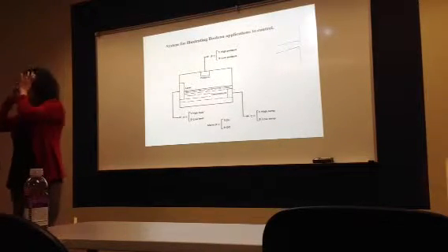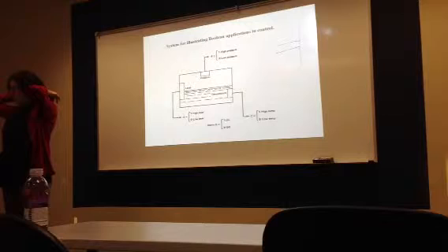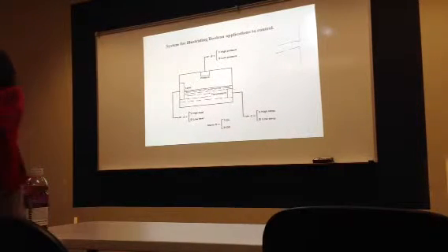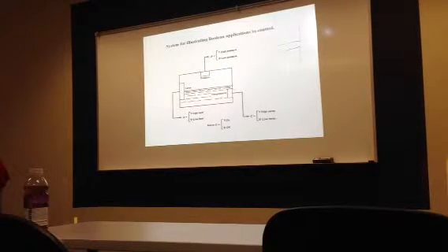Then, remember when we started to talk about digital, we talked about control as on-off, two-mode control. And when we started to talk about that, we started to talk about hysteresis. What does it mean? That we never send output to the final control element on-off, on-off.